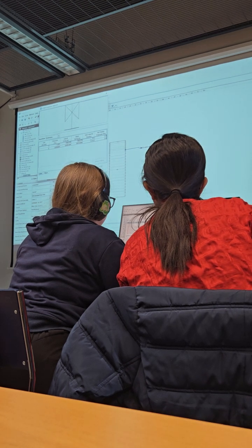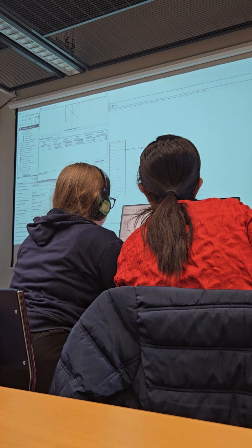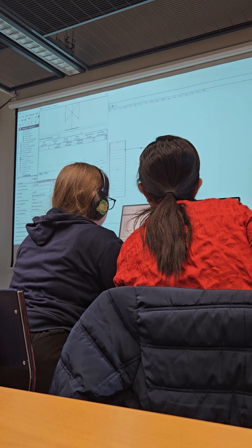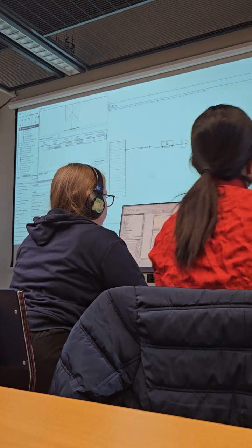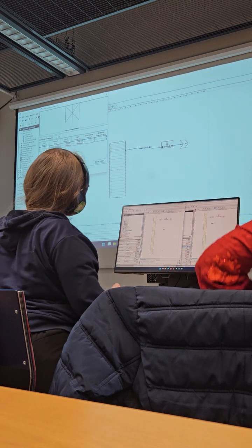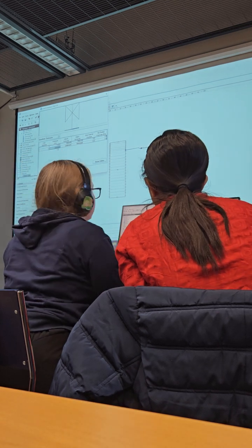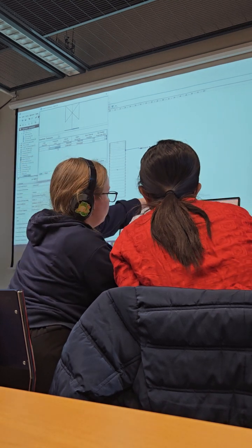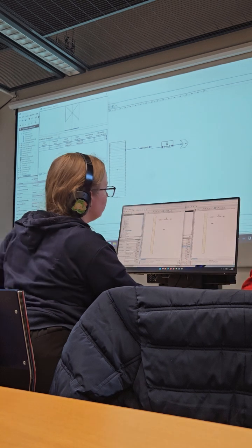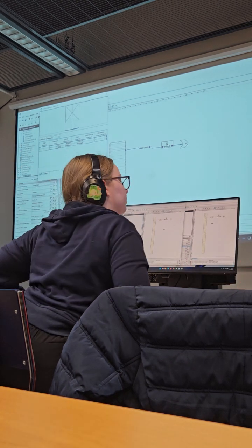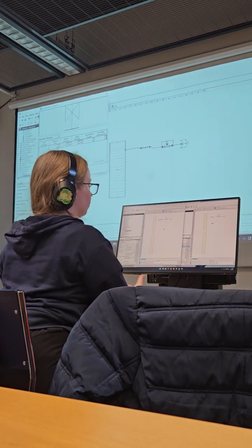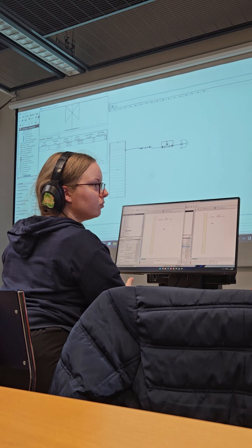It's a pure gas or steam. On the other side, we can assume that it is in atmospheric conditions because it's a closed valve, 1 bar. So 1E5. And here the boundary is here, so we can put here 1E5, which is the atmospheric.